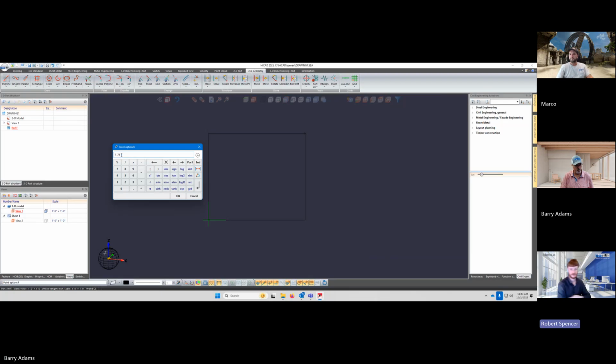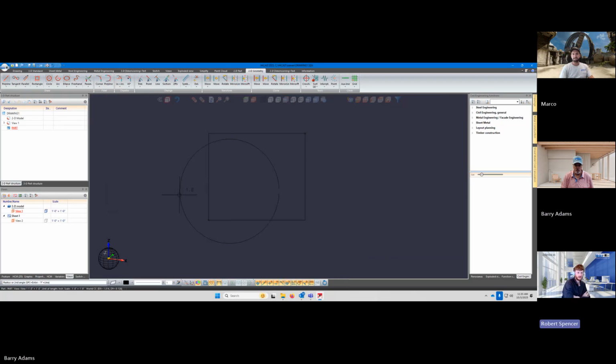We also have something called A. You'll see A sometimes. That stands for absolute. That means that the coordinates are in reference to the origin of the drawing. So now one references the drawing entities, the other references the drawing. R requires a reference point for it to work. A means the reference point is the drawing origin. So now click OK or hit enter, and now your circle. While it might not seem like it, if you make it a little smaller, you see that your center point is now snapped to the input that you gave it.